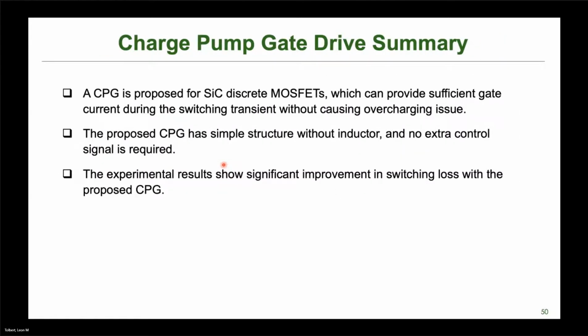And so that charge pump gate drive, again, it's able to provide quite a bit of current by charging up that external capacitance and then just dumping it in. It's a fairly simple structure, not a lot of extra control or signals or anything like that.